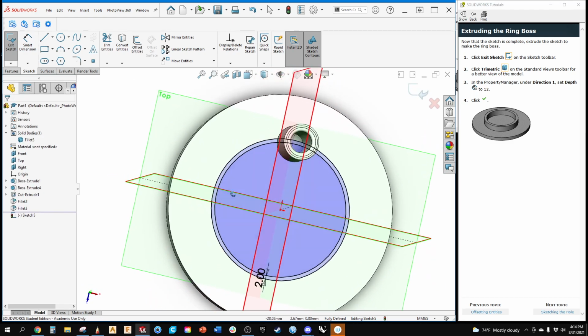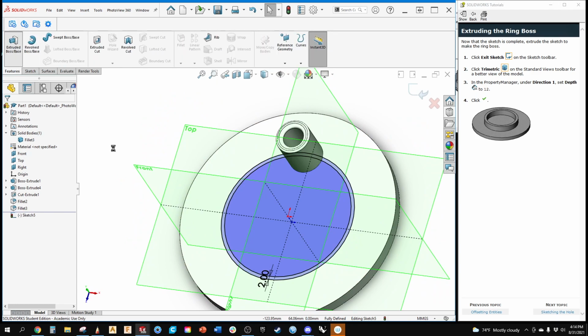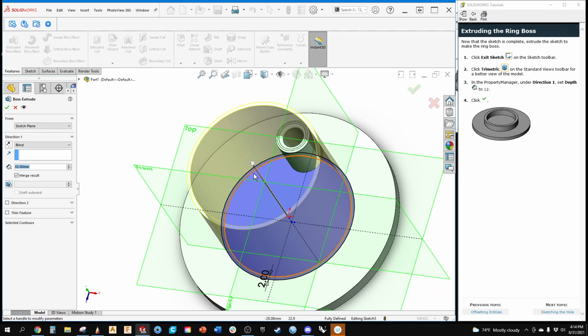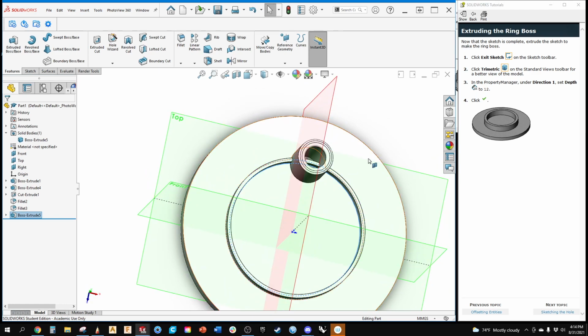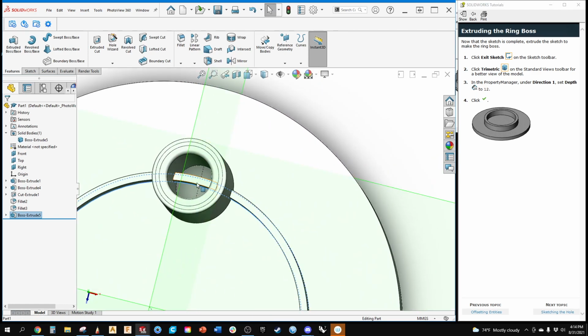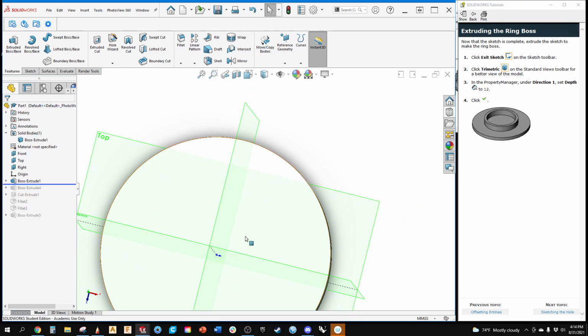And now I want to extrude it. Let's only go so high. Well, the problem is, now I've got this going through here. So then I would have to re-punch a hole. Versus, if I had rolled back up here and drew it first and then did the other one.